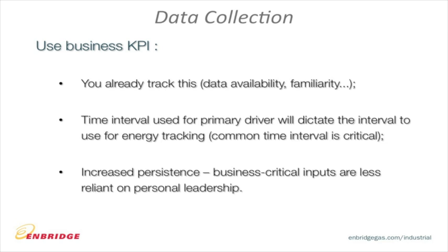Later on we'll talk about baselining, about what is normal, how much energy should we use. If you have that historical information, now you don't have to wait another 6 months to collect the information. You already have it. You can analyze it. Secondly, you will know what time interval is important for you. There's no point in collecting information on energy every 15 seconds if all you're tracking is 8 hours worth of production. You're just making it more complex than it needs to be.